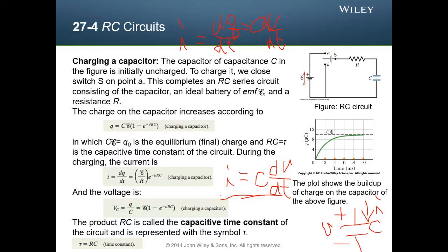So you can solve the differential equation as you have learned it. Of course, a first order constant-coefficient ODE is simple. You just substitute the first derivative, and you have the original function. So you substitute V equals e to the st, and you have s equals minus 1 over RC. So V is equal to e to the minus 1 over RC times t.